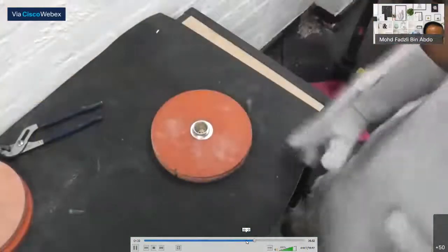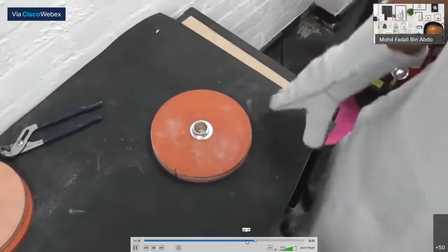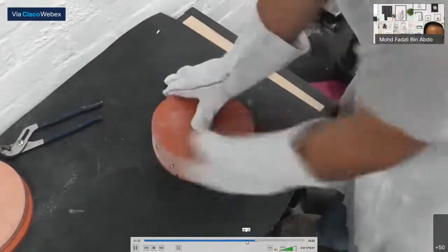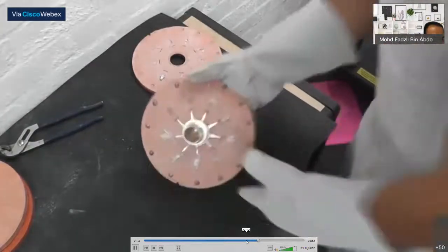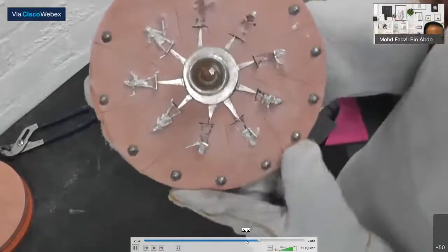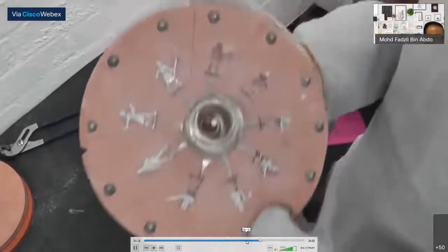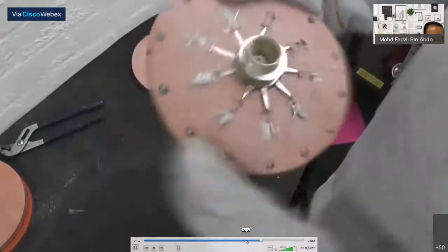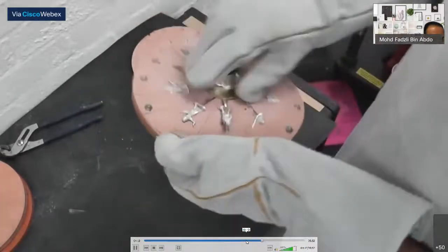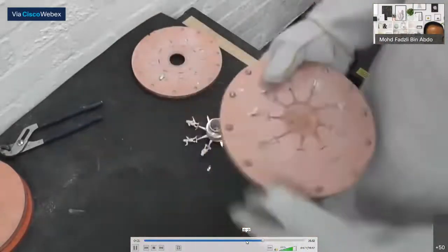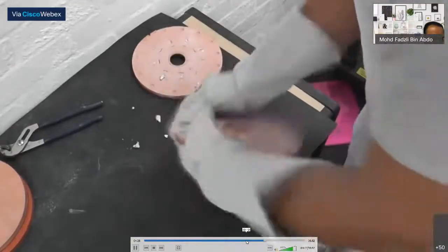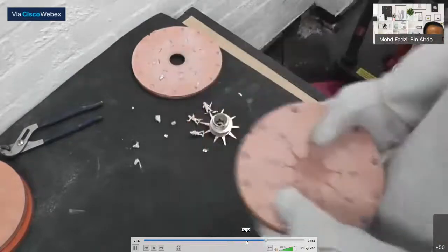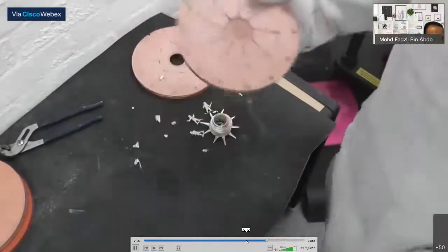So here's the mould. This is a little bit cold, so I wouldn't be surprised if everything doesn't come out. There we go. We can see that the mould's not complete. Because it is cold, it'll take a couple of spins for the mould to come up to temperature, and then it's just a matter of popping these out. You clear this all off. All of this will go back into the furnace and melt down, and we'll retap this and pop it back in the mould again.